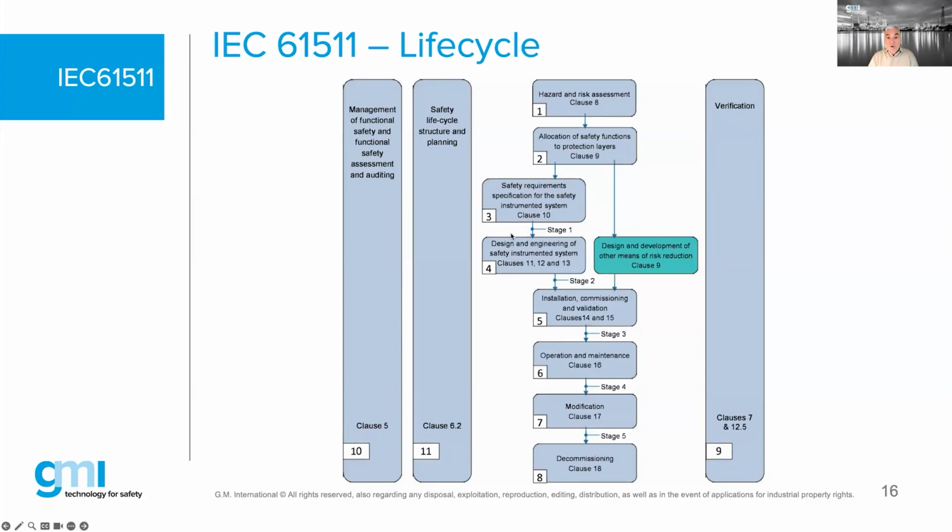And of course, once we are designing and engineering the system, this HFT will be the driving factor for me as an engineer to know how many instruments potentially I need to achieve this certain SIL requirement. Once it is installed and commissioned, it is already too late, because it is already predefined how many you would have needed in order to achieve a certain SIL class.